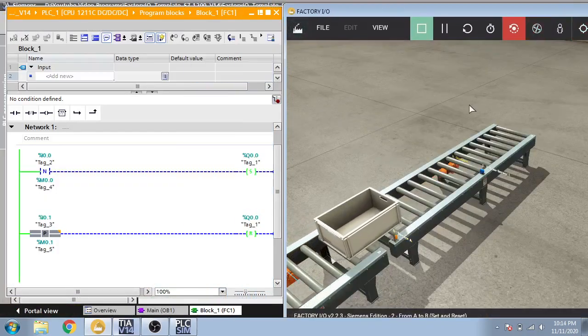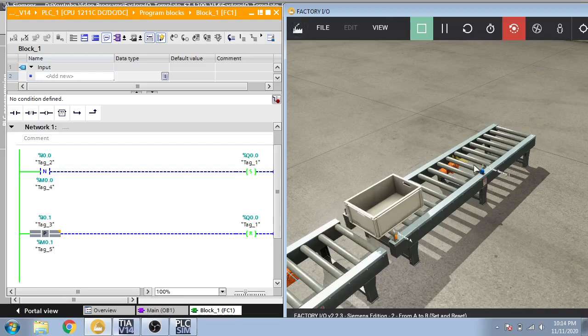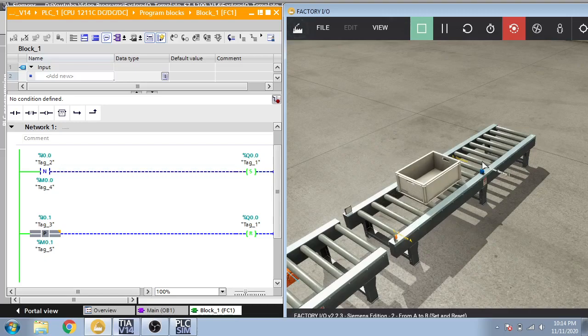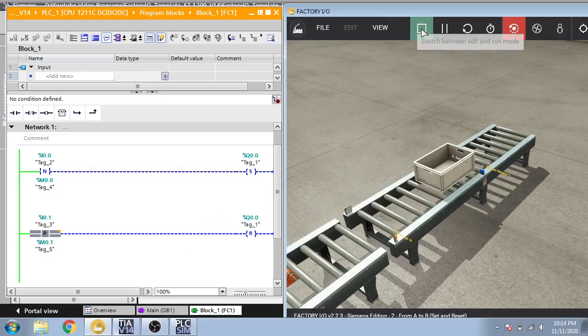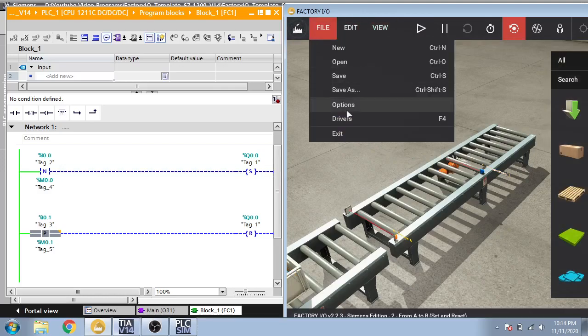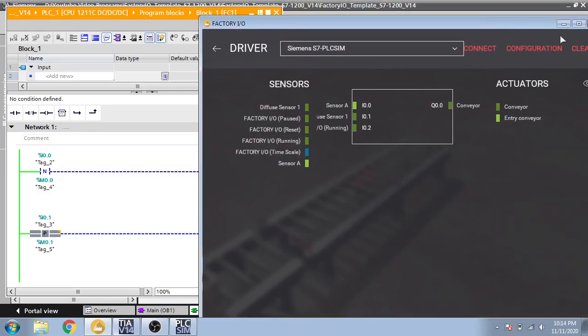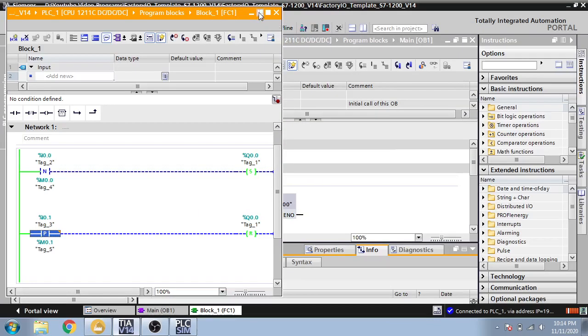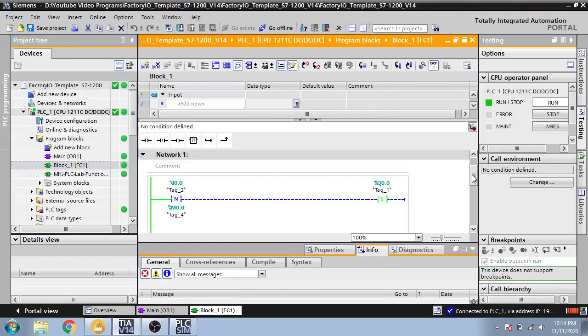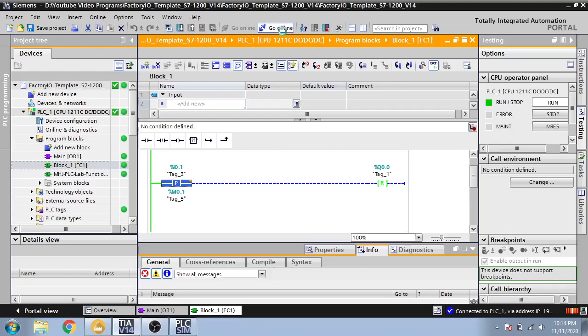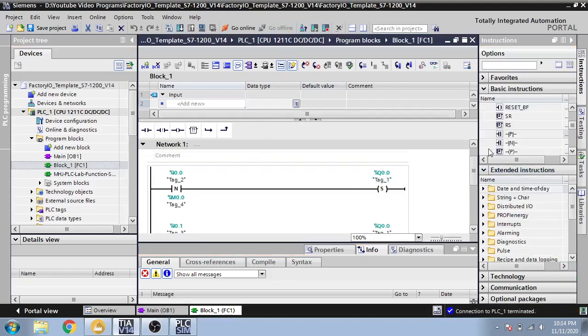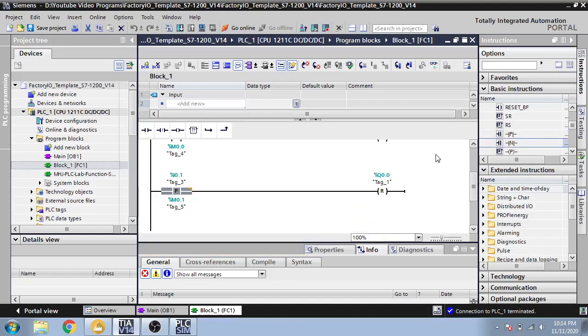You can see it going there again and again. It touches the sensor. Our logic is a positive edge, which we use with an NC sensor. Now we are using a NO sensor, so I'm changing my logic again. I'm going offline, and I'm going to use a negative edge there. You can see the negative edge.